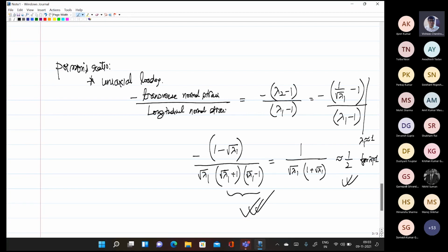Sir, in continuation with this question only, when we analyze finite deformation problems, our Poisson's ratio keeps on changing. But when we model the material, even non-linear material models, we keep the Poisson's ratio as a constant value only, we do not change it. So is the variation not much, that's why we keep it the same, or will it not have any effect? Because in the software, even when we do geometric nonlinearity cases, we keep mu as some particular constant for that material.